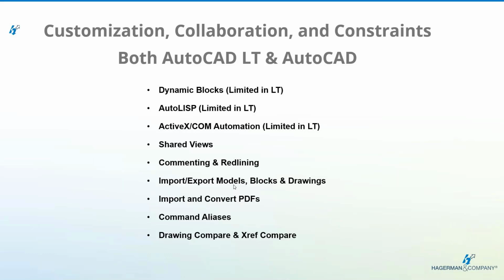Lastly, drawing compare and XREF compare. That's a pretty cool function where you can take a drawing and an older version of the drawing, or an XREF and an older version of that XREF, compare them, and it will put revision clouds around all the changes or all the differences between the two drawings. So you can kind of see if it's been a while and you don't remember, you can compare maybe Rev 1 with Rev 2 and see what changed physically in the drawings.